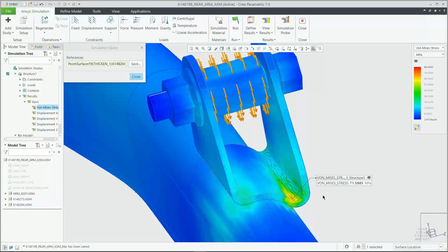So it'll be fairly quick to go through and run through those updates. And once it's updated, we can go ahead and take a look at what we got. So just a quick glance at that, we're seeing a max displacement around 0.02 millimeters. You can even get a better understanding of it by animating on that deformation if we'd like to, to see exactly how the model reacts. And we could also turn off or on the mesh visualization if we'd like to.